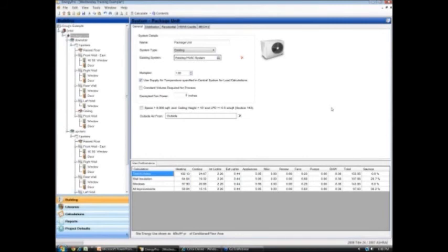Okay, thanks, Doug. The next question: for the roof and floor square foot for a 2-floor house, is it correct to divide the house's square footage by 2? If the upstairs is exactly sitting over the downstairs and there's no garage down there, yeah, that's correct. But that's not a very common situation in California.